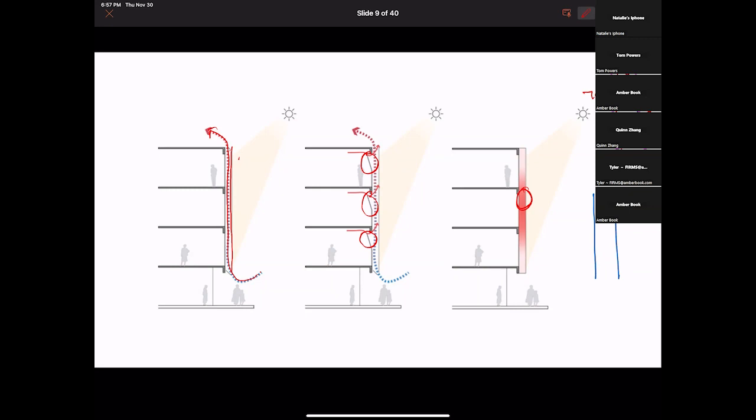Understood. And when it's summertime and really hot, it doesn't cool your building down? No, because it brings the heat in. In the summertime it's now 90 degrees outside, so it just flips around the other way. But the delta T, the difference between 70 and 90, really isn't that great. In the summertime the temperature outside is not that much warmer than inside, even on a hot day, but in the wintertime it's a huge difference. So it's usually not a summertime phenomenon we're that worried about.